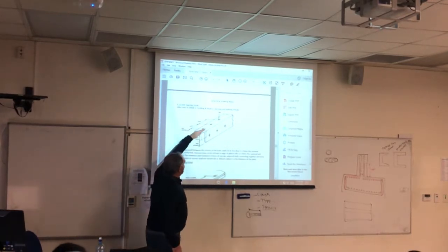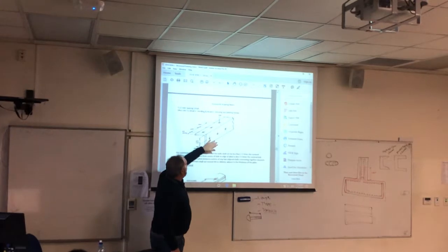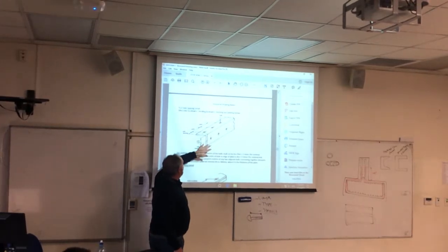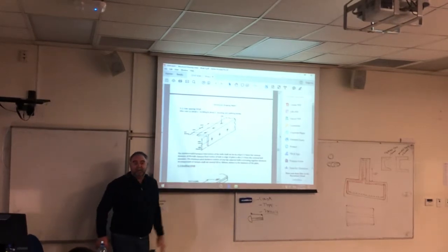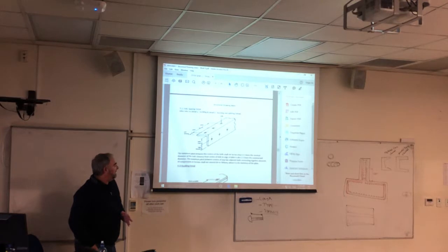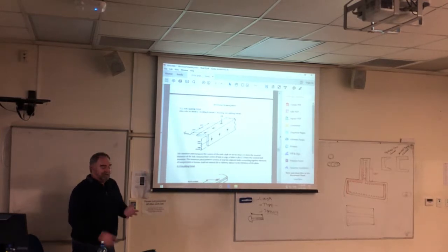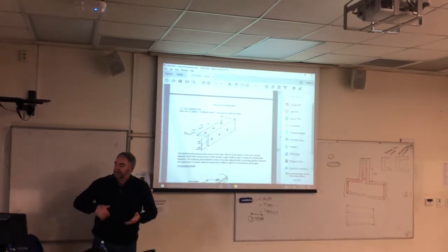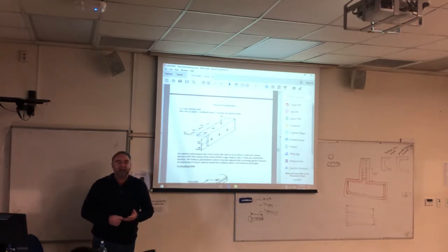But the distance from the face to the hole, and from that face to the hole as well, is called a back mark. So that's interesting. There's back marks in surveying, which is totally different. And in dimensioning angles and members to the holes, we talk about back mark when it comes to angles.